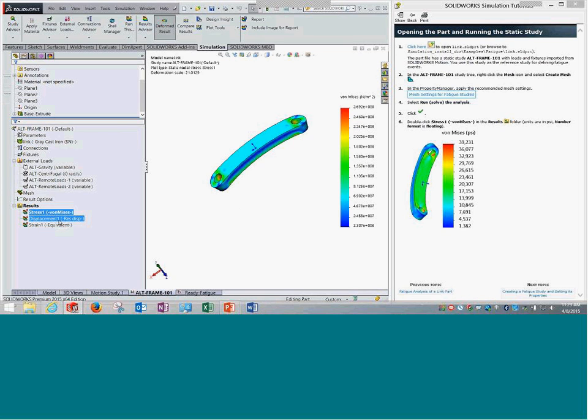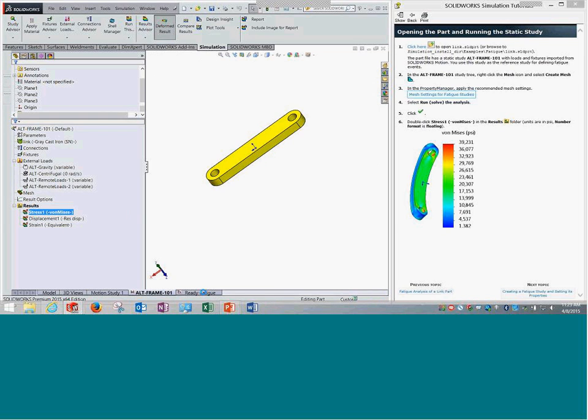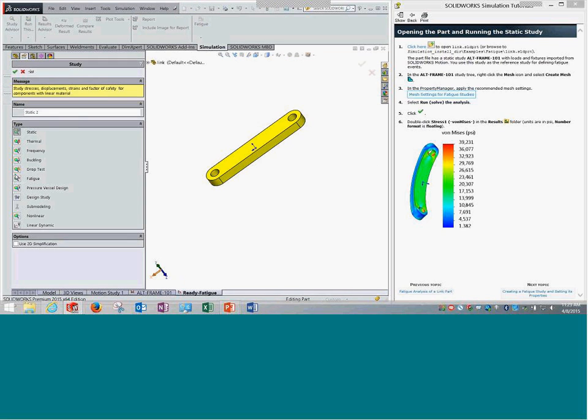I believe now you are comfortable how they look and what they are all about. So, I just created a new study for static analysis. I also create one over here for fatigue analysis. Loads can be as what I have shown you now, so be variable, that is they can be random loads, can be harmonic. They can also come from a random vibration analysis. So these different options are there. I am taking the first option now and proceeding.